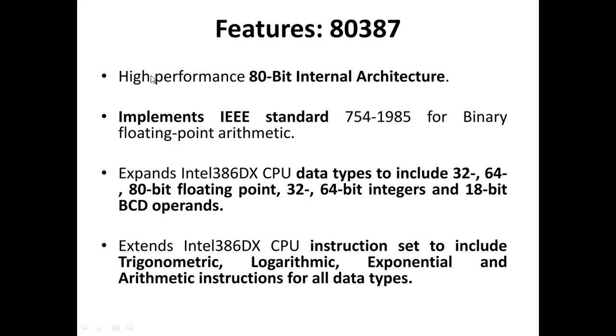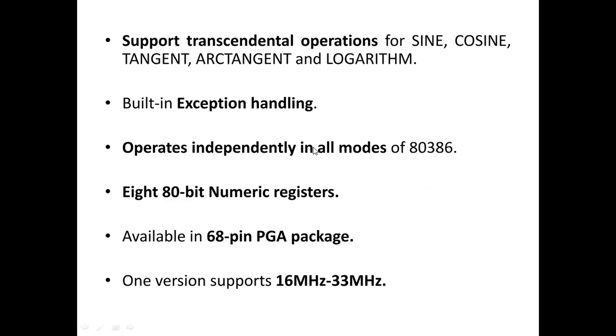It extends the Intel 386DX CPU instruction set to include trigonometric, logarithmic, exponential, and arithmetic instructions for all data types. It supports transcendental operations for sine, cosine, tangent, arctangent, and logarithms. It has built-in capability for exception handling. It operates independently in all modes of the 386, which may be real mode, protected mode, or virtual mode.